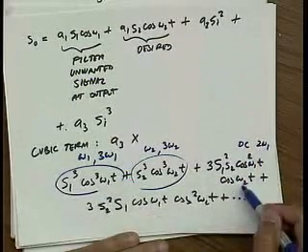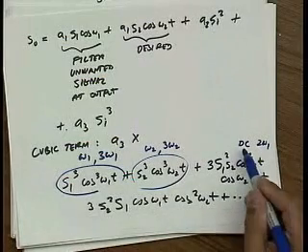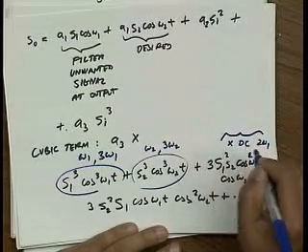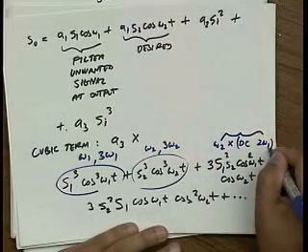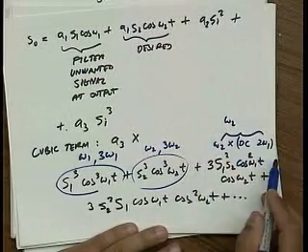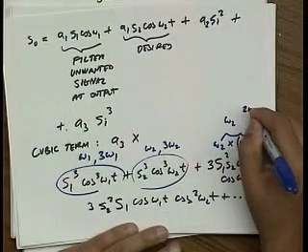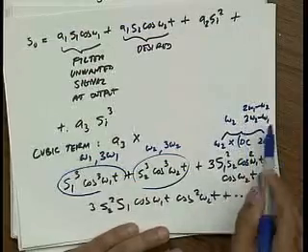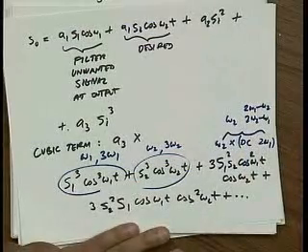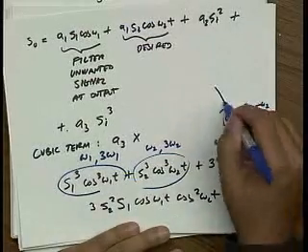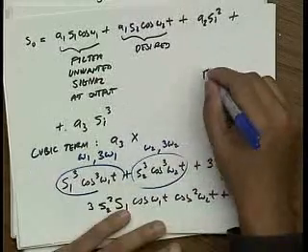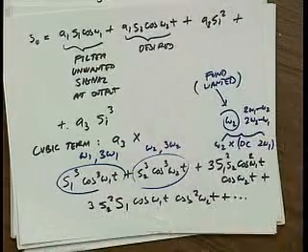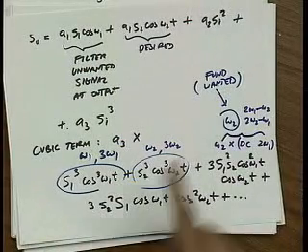And when I multiply it out by this term, I'm going to get omega 2, and I'm going to get intermodulations 2 omega 1 minus omega 2 and 2 omega 2 minus omega 1. Okay? Well, this is the term that I care about. This is my fundamental. This is the wanted. So let me focus on this term.